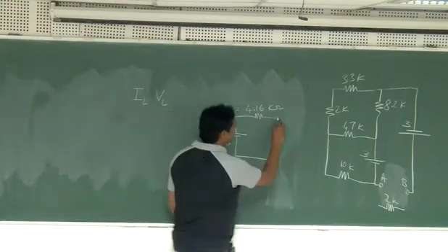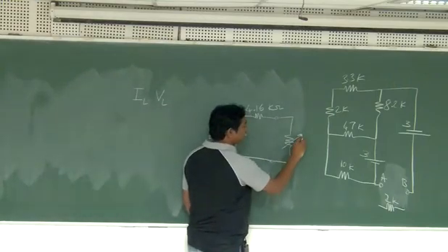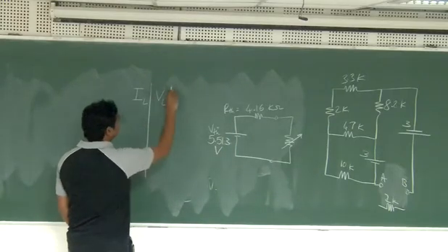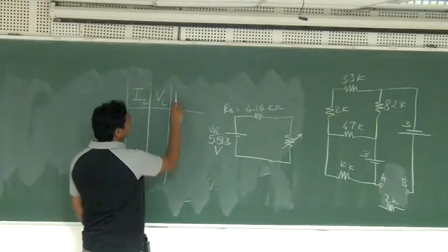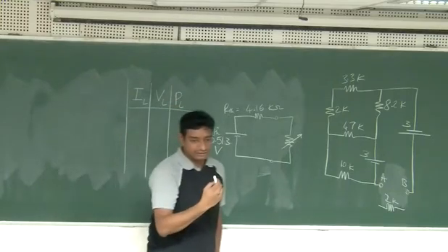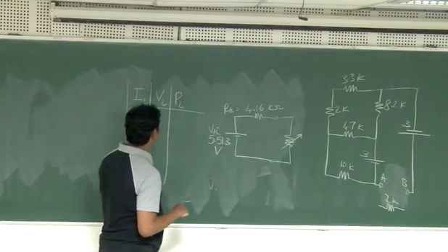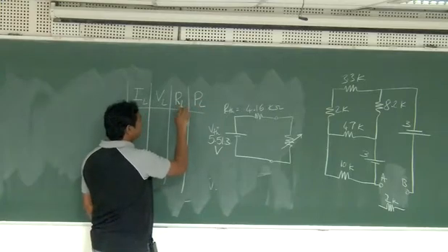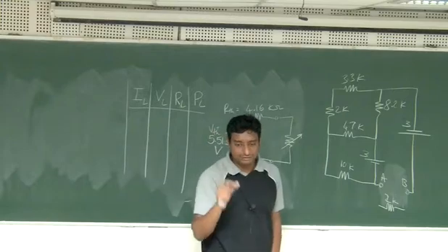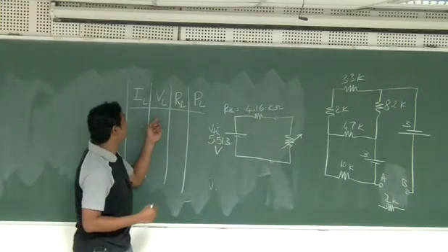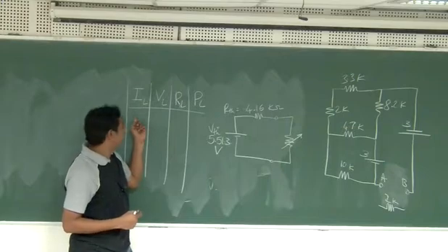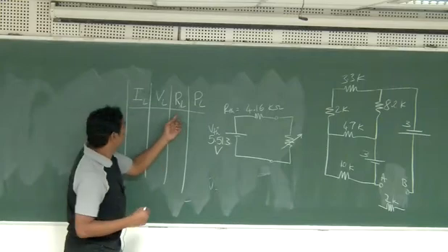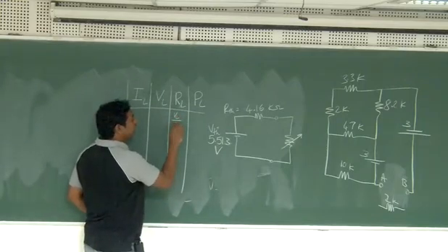So what I'll do is I'll put a variable resistance. The resistance I can change it. Okay, so I'll show it to you. So the current into voltage, I'll get the power. So this is power in that load resistance, and then the load resistance value itself, because I'm changing that value. So how to calculate the load resistance value? Simply voltage divided by current. Okay, because it's just Ohm's law. So this divided by this, I'll get the value of RL. So this is VL divided by IL.